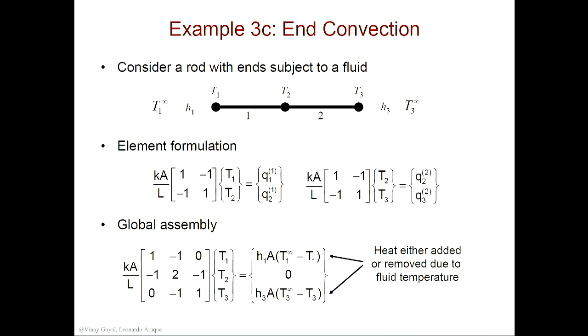It has an essential boundary condition and also a natural boundary condition. Okay, it's a mixture of the two. I have an essential type of boundary condition showing up on the right-hand side, but I also know that this is like a heat flux. So I have a mixed type of boundary condition. Okay.